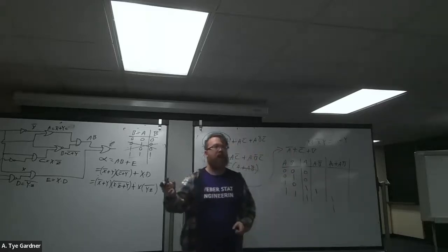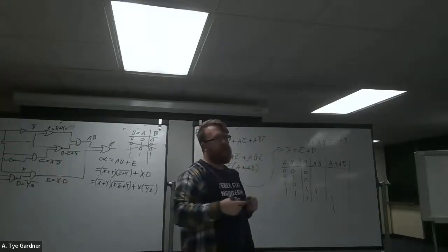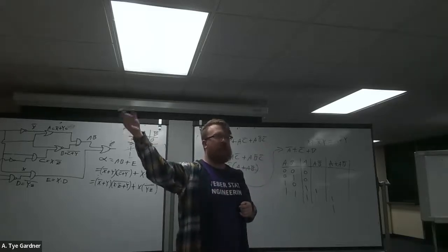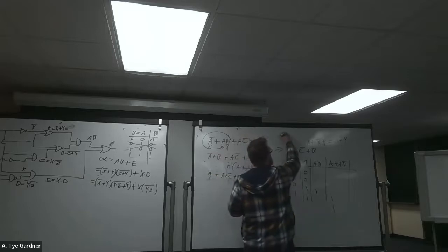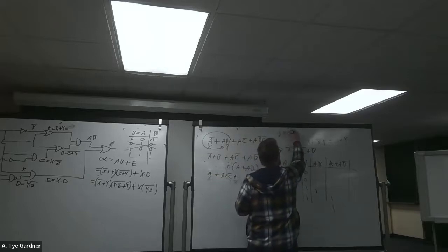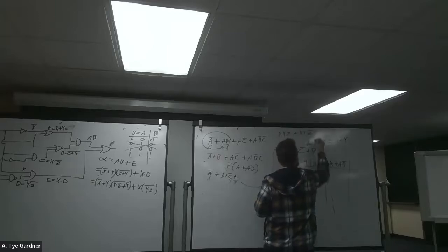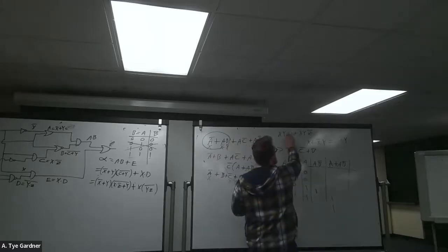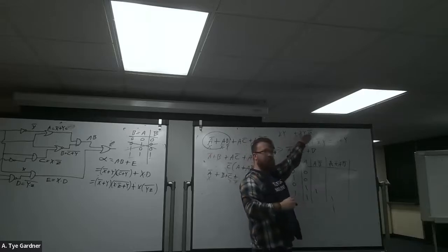So basically what it's saying is anytime I have an expression that is ORed with another expression and one of those expressions is smaller than the other one, but the same, it goes away. And it extends more complicated a little bit. So let's say you had, let me do that this way, X and Y or X and Y and not Z.